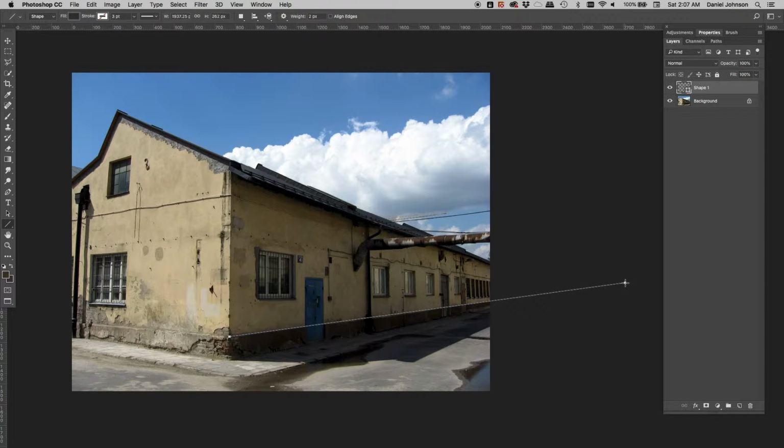Now I want to add more lines to the same vector shape layer. So I'll hold down the Shift key. You should see a small little plus sign there. And we'll click and drag, and we'll just drag this up by something that should match up and be pretty much parallel. I'll go right here. Great. So we've got these 2 lines, and they aren't where they need to be yet. So if I click off of this, you'll see I don't really have a great color.